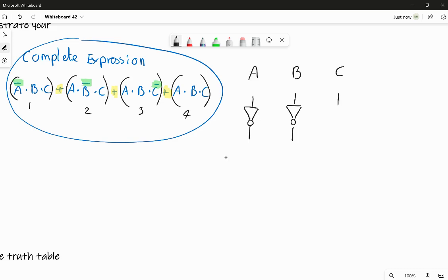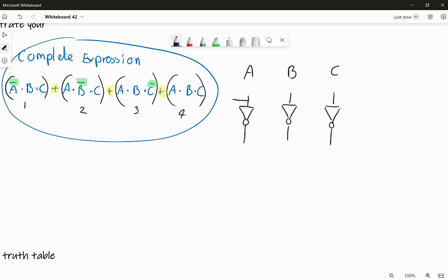And then from this we can start to look at where our inputs are going to go. You don't have to do it like this, you can have them going across. The good thing that I like about this way is you can actually take a standard A input from there, and then not A from underneath, so it gives you a little bit more scope and options to personalize your circuit design. So what we're going to have now is our first AND gate.